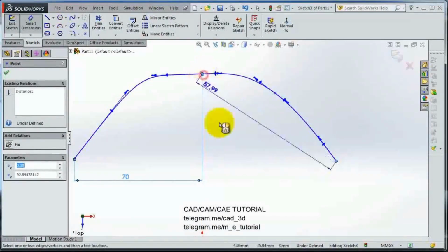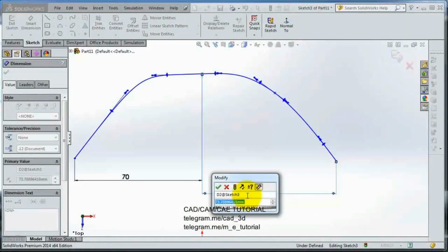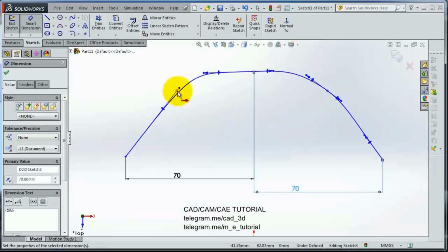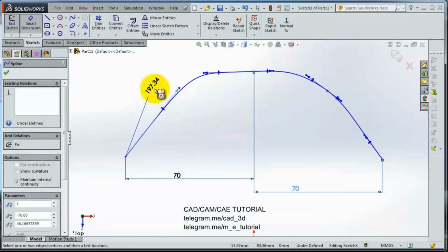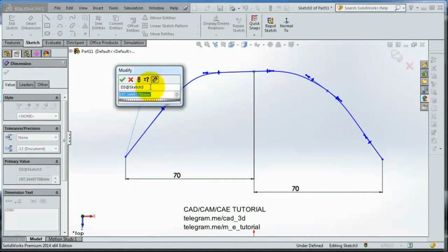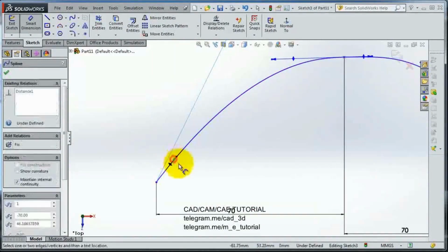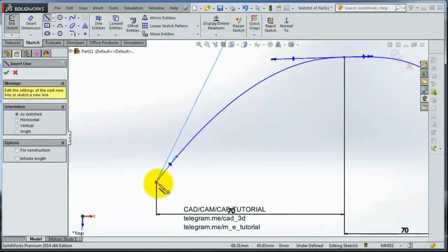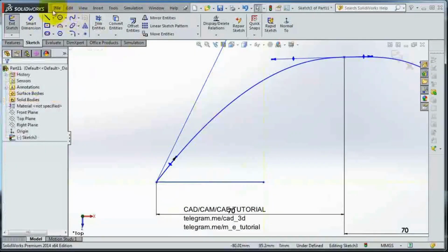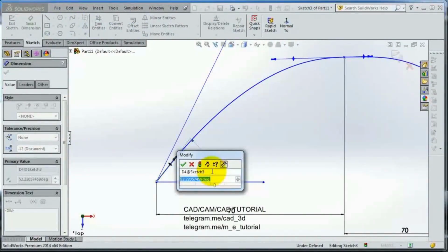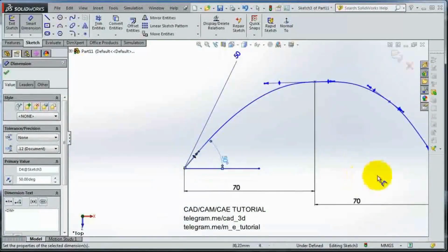And in the spline you can add dimensions as well. You can select 2 points and add a dimension between them. This is one way to control your spline. Also, we said you have size and direction, so you are able to add a dimension for that. So let's add size for your handle. You can add 50. You can notice the difference, and also you have an angle.